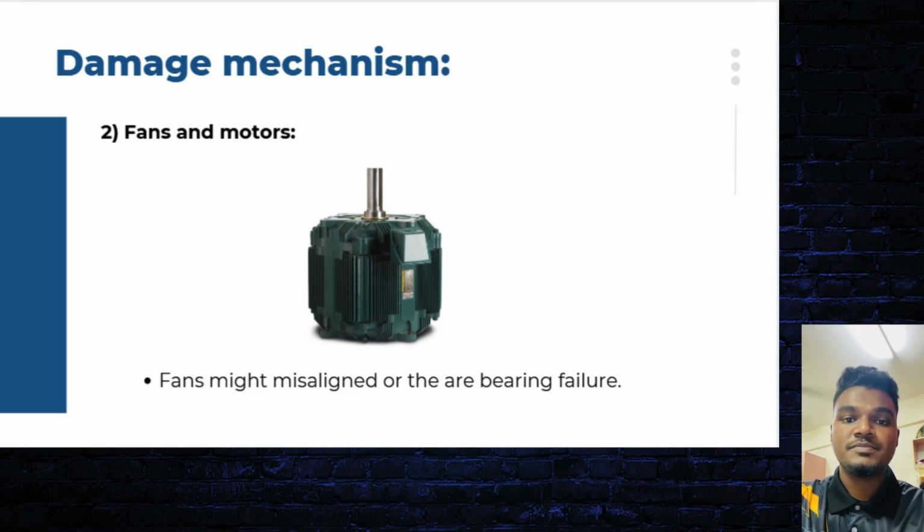One common issue is misalignment, which can arise from improper installation or assembly and be exacerbated by vibration due to unbalanced blades or components. The effects of misalignment include increased vibration leading to structural fatigue, as well as reduced fan efficiency and higher energy consumption. Another prevalent problem is bearing failure, often caused by contaminated lubricants along with overloading or improper alignment of the shaft.